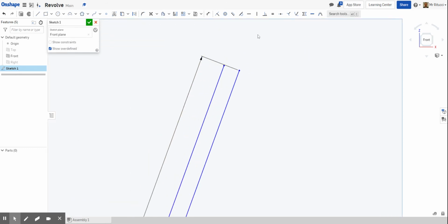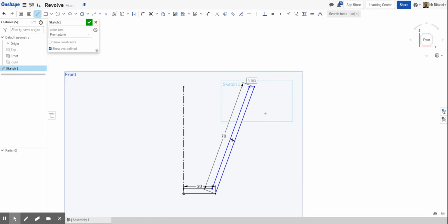This one, I want this top to be flat. So what I'm going to do is click that dot, then click that dot. Okay, at the moment it says, I'm going to click that one, and then I'm going to click horizontal. Which means then these two are level. So with that, I'm going to click across here to join the top. It's going to be a nice flat top.